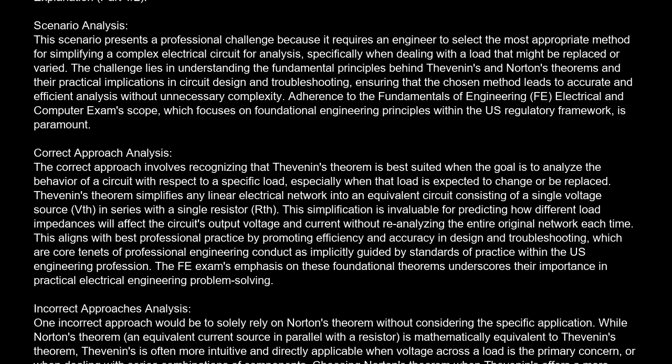Correct approach analysis. The correct approach involves recognizing that Thevenin's theorem is best suited when the goal is to analyze the behavior of a circuit with respect to a specific load, especially when that load is expected to change or be replaced. Thevenin's theorem simplifies any linear electrical network into an equivalent circuit consisting of a single voltage source, VTH, in series with a single resistor, RTH. This simplification is invaluable for predicting how different load impedances will affect the circuit's output voltage and current without reanalyzing the entire original network each time.